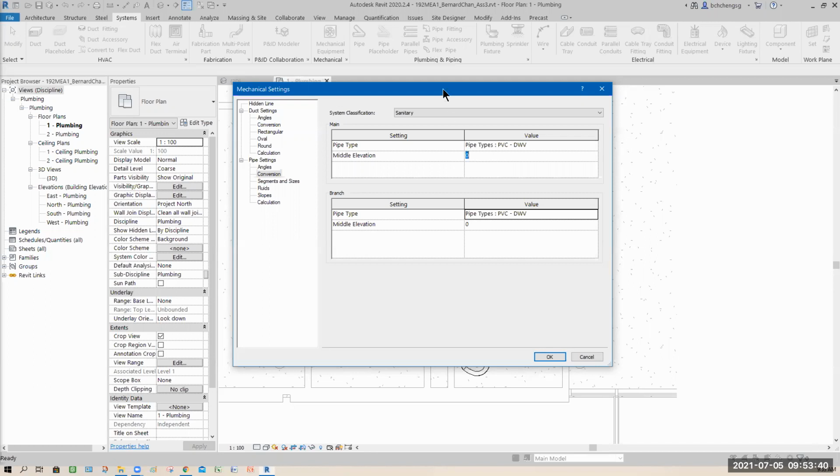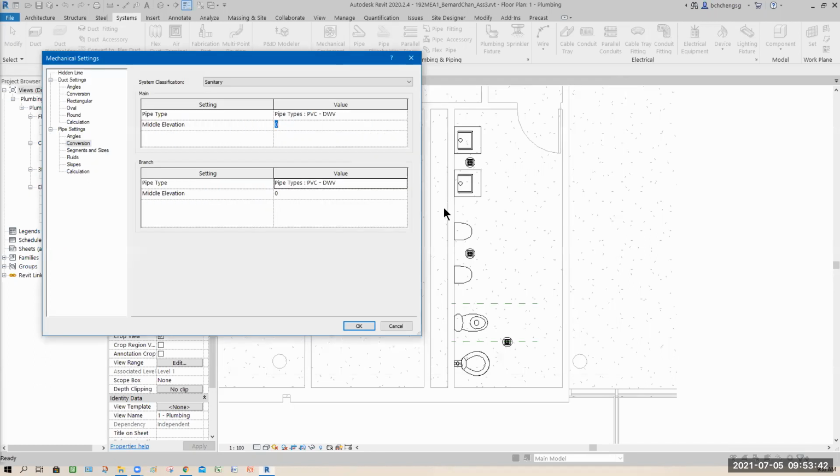If you don't adjust, you can see that later when we add this sanitary pipe, it is floating on the surface. Gravity means they must be lower or different from the standards. That means the floor level, it should be lower, cannot be higher. So always lower. Okay, so let's say you guys follow your notes.